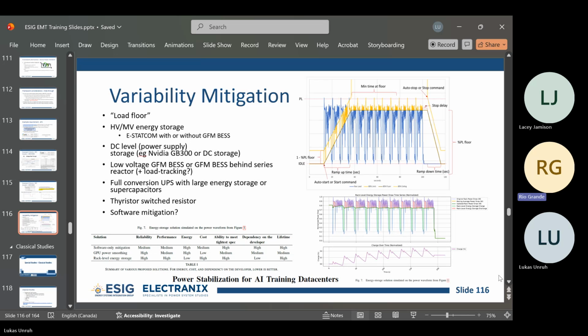That was determined to be big enough to worry about. And now for those IBRs, I think it's 60 kV and 20 MVA. So there are good reasons to treat some differently than others, because they could have a massive effect.